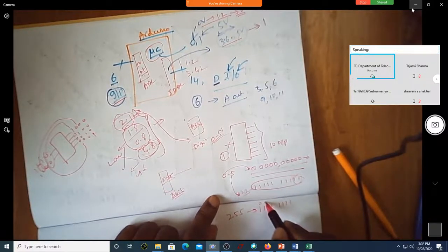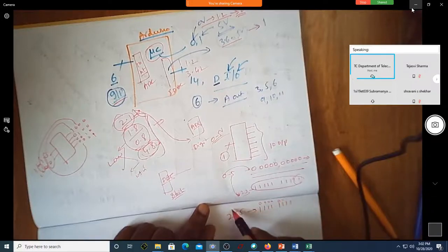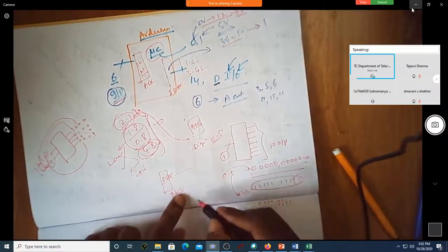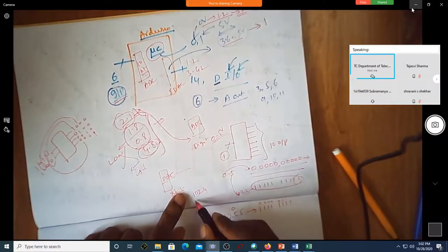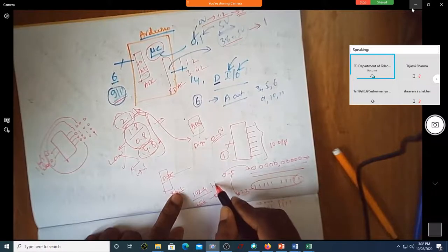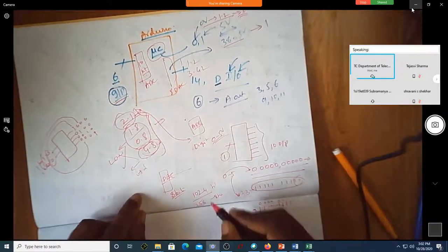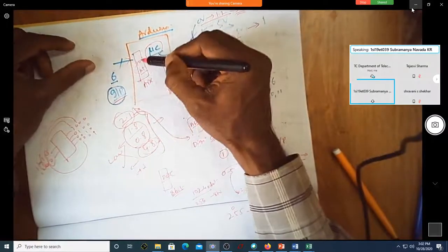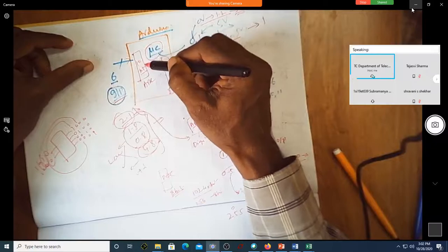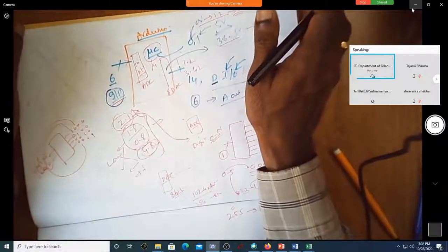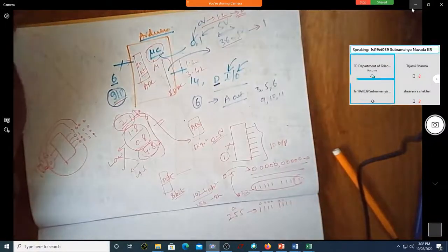So including 8 zeros, the range from 0 to 255, this is 0 to 1023. You can see 1024 is the range for 10 bit, 256 is the range for 8 bits. So how much is the ratio? 4. So that's why whenever you read the value inside, because it's 10 bit, if you want to write the same thing onto this, it has to be divided by 4 and then you put it there. Then they'll be equivalent. Okay, fine.